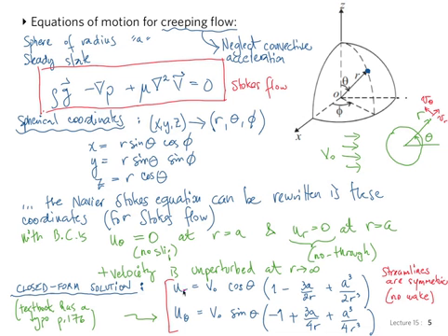And with the velocity u_r and u_theta, we can find the pressure. I'm going to now clear these annotations to write down the expression for pressure, and finally the expression for the drag force, which is the most famous result for Stokes' drag, this drag around a small particle, which is, for example, a particle settling in air, or a small particle settling in some water. So it's a very standard, famous result, the force of drag in that situation, when the particle is moving at a terminal speed and a constant speed due to complete balance between the weight and the drag force of the fluid.